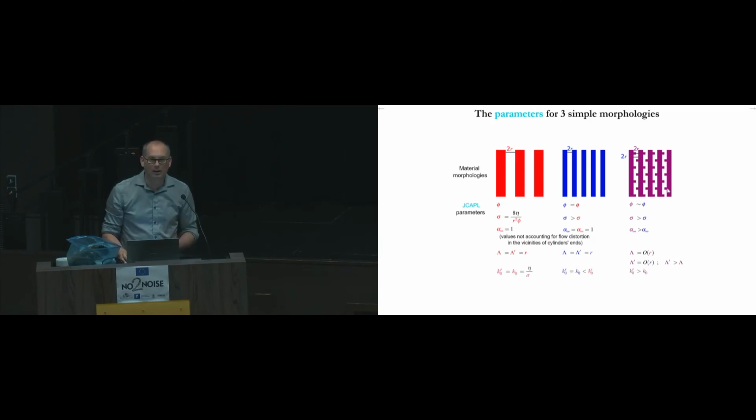We can also compute the static thermal permeability. And as I said, if you have the morphology, you can compute the value of these last parameters introduced by Pride et al. and modified by Lafarge. So you have these values for straight cylindrical pores, and you have these relations for a more complicated structure. So I will let you play with this example, with this exercise if you want.